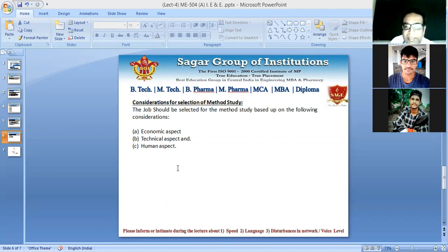First of all, bottlenecks should not appear during the production operations. Second is operations that involve excessive labor involvement or movement. Third is operations producing a lot of scrap and defects. That includes cost, as I discussed with you in the previous slide. Then comes the operations which have poor utilization of resources. Sometimes we can say underutilization of resources, and sometimes it goes to over utilization as well.